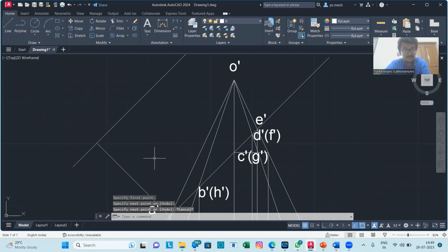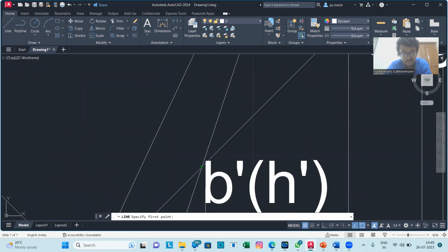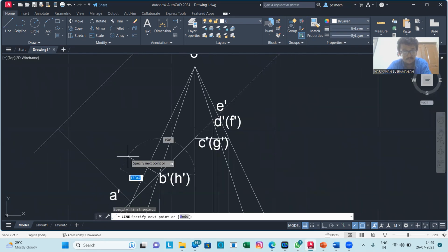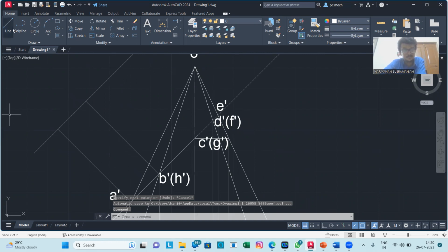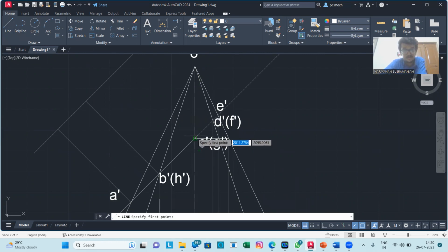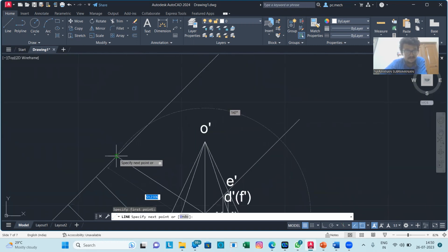So I have drawn the first line. Similarly, you have to draw for all the cutting points. So this is another cutting point. I have to draw for all the other cutting points as well. So you are seeing the L here, whenever you see the L shape. For this to show, at the beginning of the drawing you should make sure that the OSNAP command and all the checkboxes in OSNAP are on. Then only the perpendicular symbol will show while you're drawing, right?